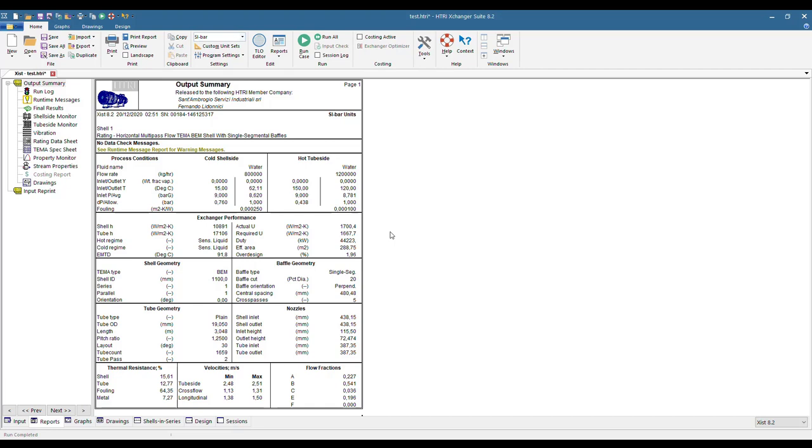So note that in these conditions, having a 2% or also minus 2% of over surface has practically no meaning, no technical meaning. But of course, if you have to prove that your exchanger is reasonably safe from the design point of view, even a 2% should be a plus 2% and not a minus 2%.